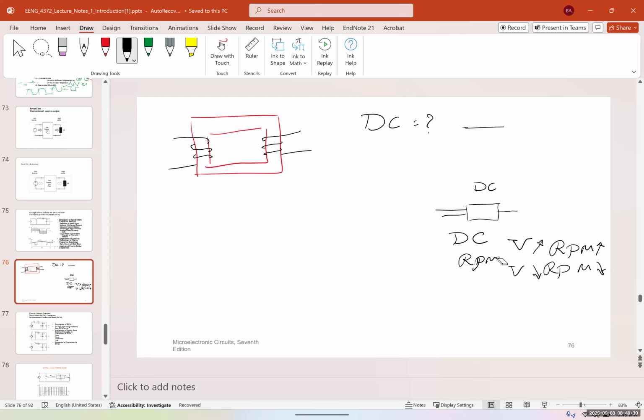So imagine the DC motor is connected. One way to do that is to use a variable resistor. Yes. To do that, you have to be physically at the motor and adjust the variable resistor. It's not practical, first of all. Second, it's going to waste about 50% or more of the power. So this is out of the picture. Another method that we use is called PWM.